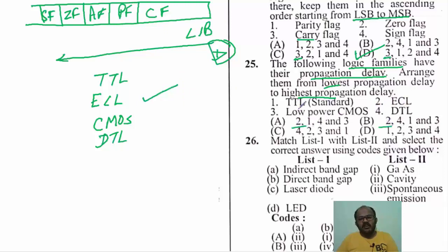In the case of CMOS family, it is going to have less power consumption. You can classify the power consumption into static power dissipation as well as dynamic power dissipation. In the case of CMOS, the static power dissipation is approximately equal to 0 and the dynamic power dissipation is given by f C_L V_DD squared. So I can tell it is having less power consumption, nothing but more delay will be there. So CMOS will be having more delay.